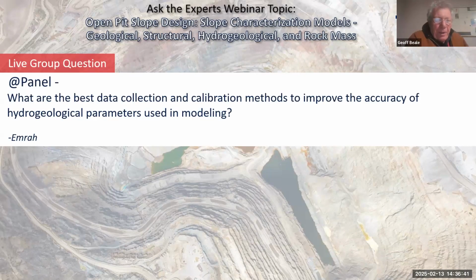then we know the hydraulic system has boundaries and lots of structural control, and the flow system isn't continuous. So piezometers are the fundamental. Piezometers and cross-hole testing is the fundamental method. Great. Thanks, Jeff. Expert answer as always.